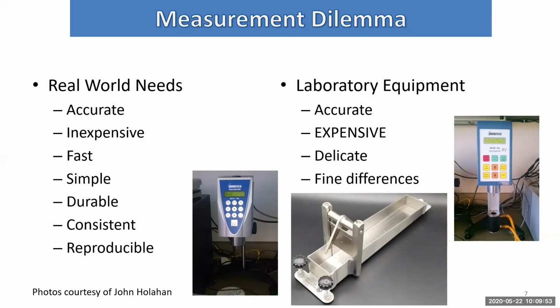In fact, they usually take their measurements by spinning on a delicate glass jewel, and I've had to send machines out for repair the day after I received them due to mishandling by untrained employees. But even with these limitations, these low-end viscometers still cost at least $2,000 US each. And if you wanted to get a full-fledged rheometer that can precisely control things like temperature and shear rate, you would likely spend tens of thousands of dollars.